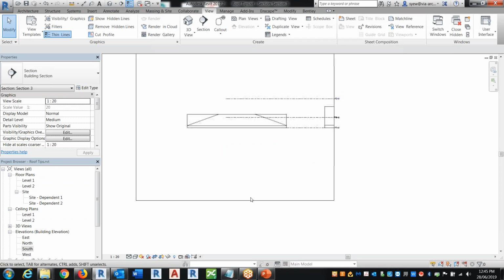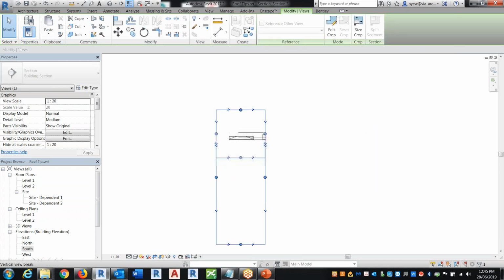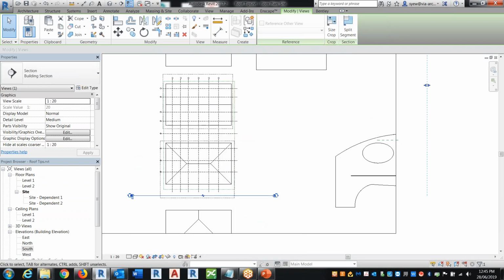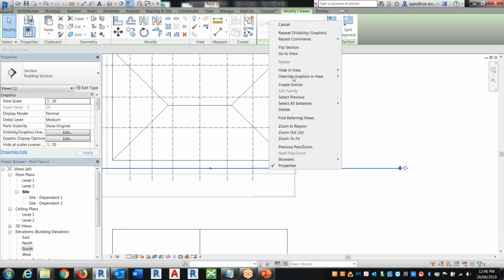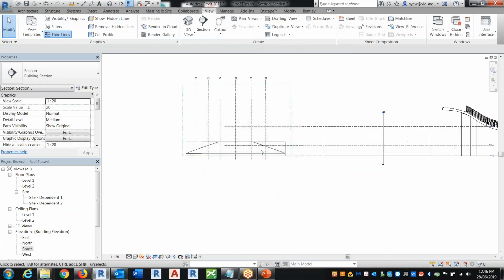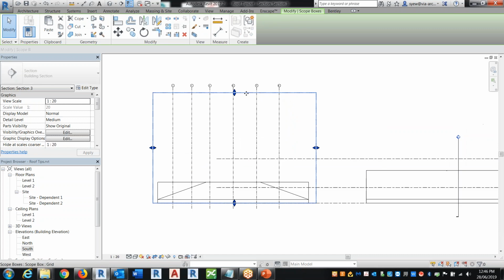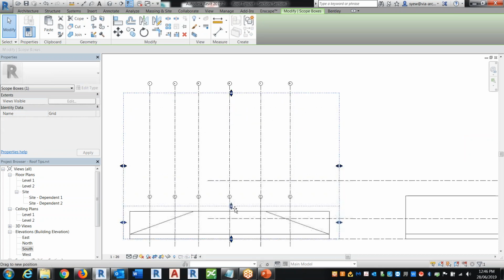Yeah, that's the difficult part about Revit, is that the grid line sometimes may not show up. Oh, actually, you know why? Because I accidentally put it away. You notice that right now, if I put it away, it doesn't show up, but if I put it closer there, there's a grid line. Now, the nice thing about this is that you can actually control where you want the grid line to be.